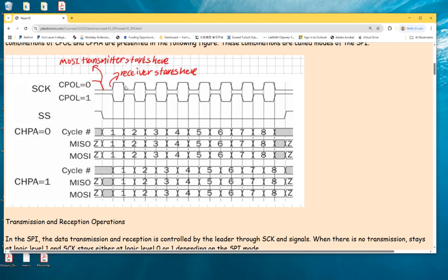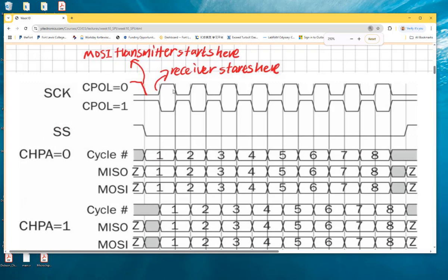If you look at this falling edge, let me zoom in a little bit. At the falling edge, it's during the data transition. It's not in the middle of the data. Okay? So that means it's not sampling. But what you can do is let the leader just drop the data to the line, but the receiver is not taking it in.